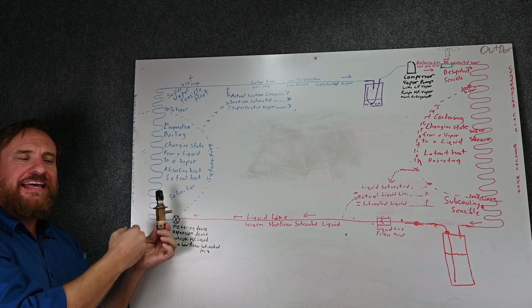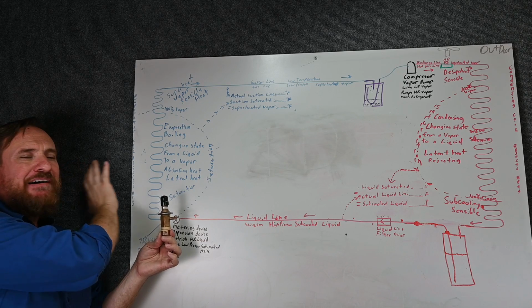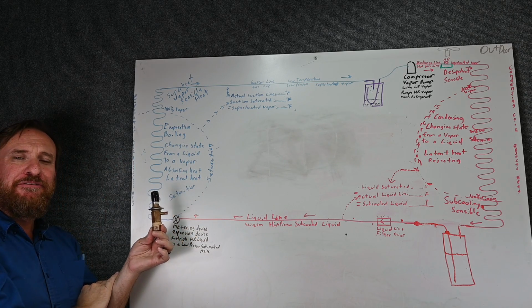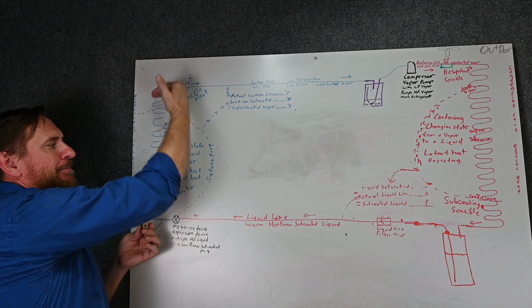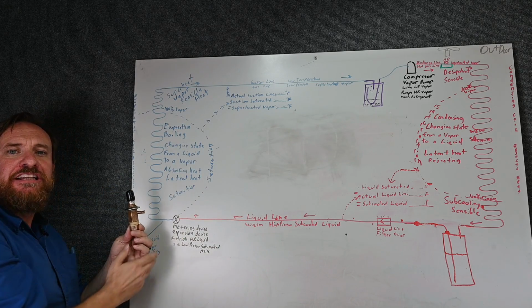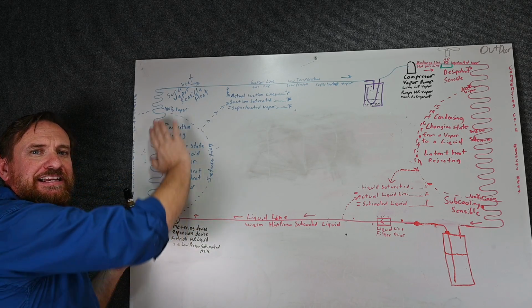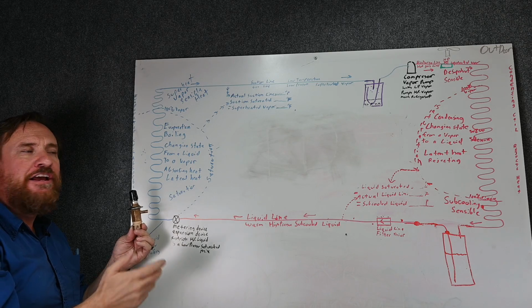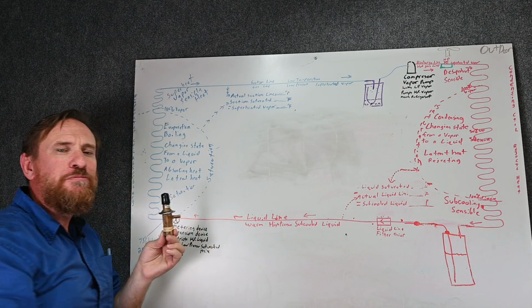Now by doing that, we end up with more liquid in the evaporator coil. So remember, now I have less heat against my evaporator, and now I also end up with more liquid refrigerant in my evaporator. So what will happen is I'll end up flooding my evaporator. All of this could be at saturation, liquid and vapor together. So here I could still be at 121 psi gauge, but all of this is liquid refrigerant. I have 0 degrees of superheat. With 0 degrees of superheat, that means I'm getting liquid refrigerant all the way back to my compressor.